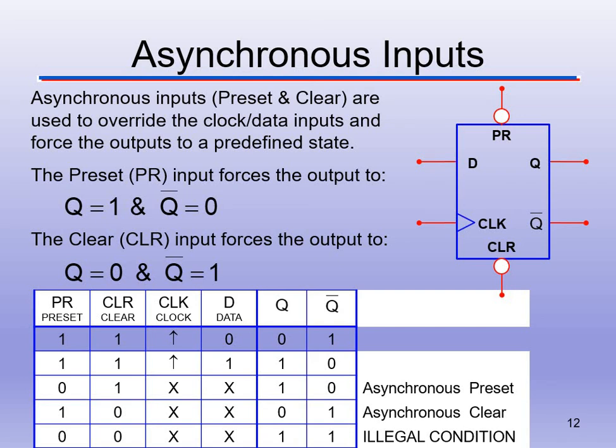All right. Now we can make asynchronous inputs. So we've already done this a little bit in one lab, but what we can do is add a preset and a clear to this situation. Preset is going to send the signal to 1, clear is going to send the signal to 0. So that's very, very important if we have a preset or a clear. And notice the states and when that happens. Notice that there's inverters on the preset and the clear. And that's the D flip-flops that we're going to be using in class, the 74LS74s. They're both inverted there, so whenever we get the opposite signal.